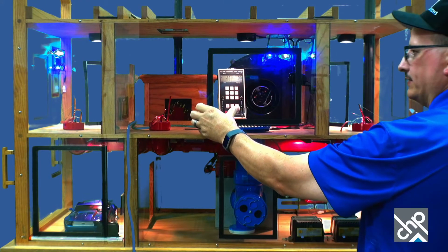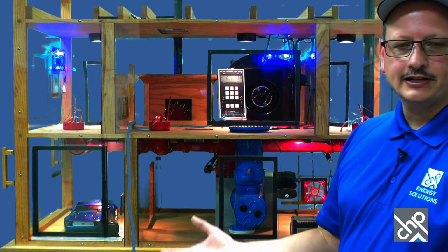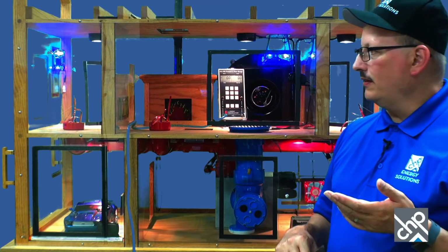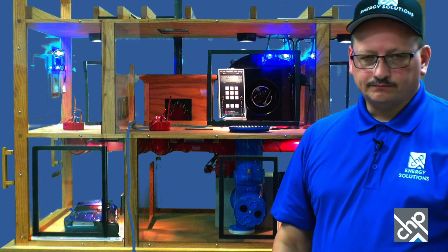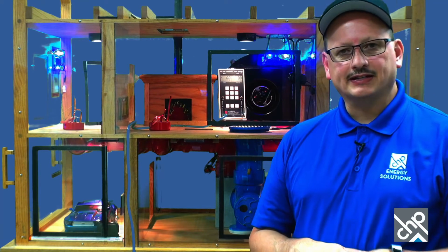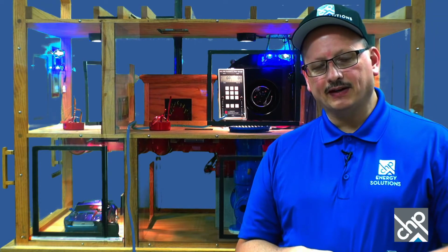And I'm going to take the window completely off. So as soon as I do that, the pressure gets relieved. So like you saw there, we didn't have a problem with the smoke going out the chimney until we tightened up the house. So it's really important to do combustion safety testing when you have a combustion appliance, and make sure smoke goes up the chimney.